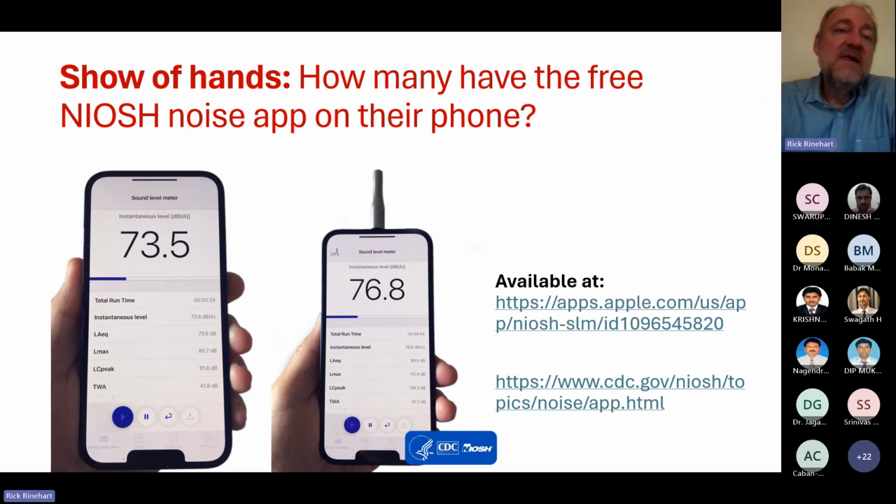So this is my last slide, and I'm just curious how many people on the webinar today have taken advantage of the free NIOSH Noise app on their phone. It's an incredible app. Unfortunately, it's only available for iOS devices or iPhones, but it can be used with an external microphone, and when it's calibrated with an external microphone, it meets the Type 2 requirements for sound level meters, and it's totally free. If you don't have it and you have the opportunity to use it, or you have a colleague who has an iPhone, I recommend you get it and start using it in your workplace.